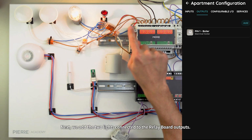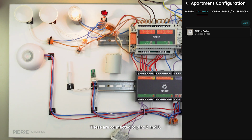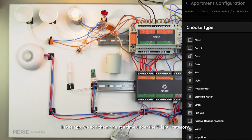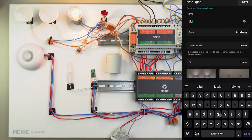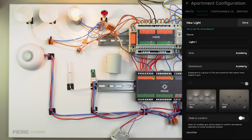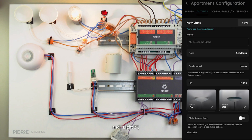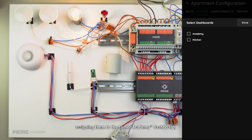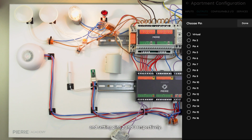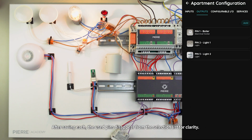Next, we add the two lights connected to the relay board outputs. These are connected to pins 2 and 3. In the app, we add them one at a time under the light category, naming them Light 1 and Light 2. Assigning them to the same Academy dashboard, and setting pins 2 and 3 respectively. After saving each, the used pins disappear from the selection list for clarity.